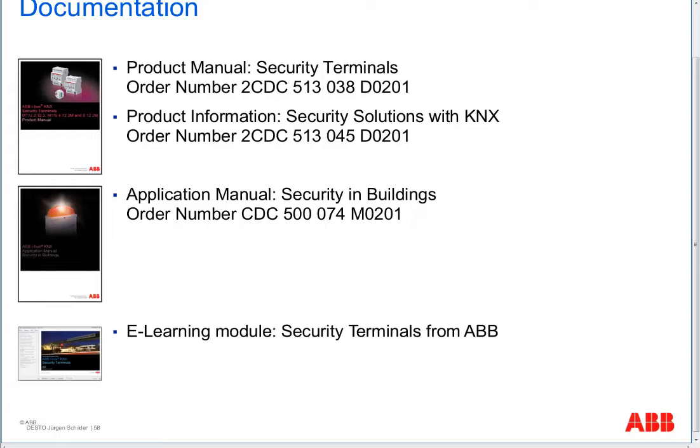It is possible to use maybe the comfort panel. The comfort panel has also some basic logic for security inside, but don't mix it. Use the security terminals for the alarm logic, and for example in the comfort panel only the buttons to send commands: go internal set, go external set, or reset. So don't mix alarm logic in the panel; use the alarm logic in the security module.